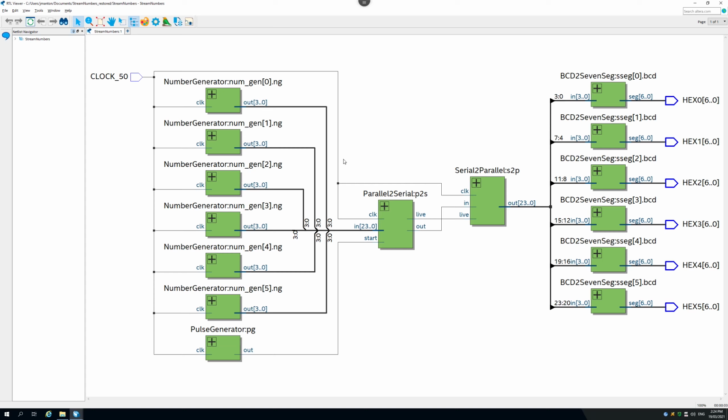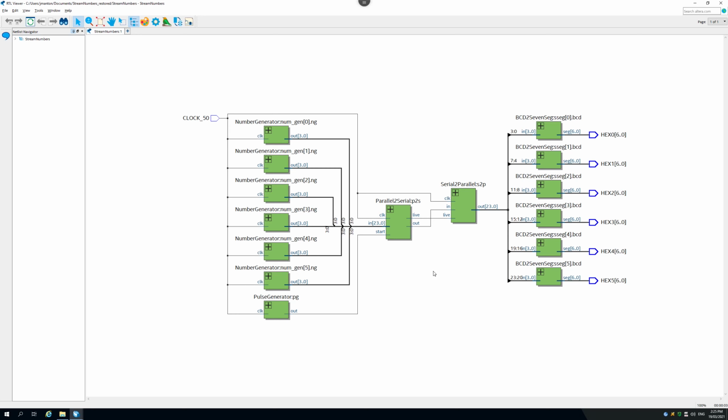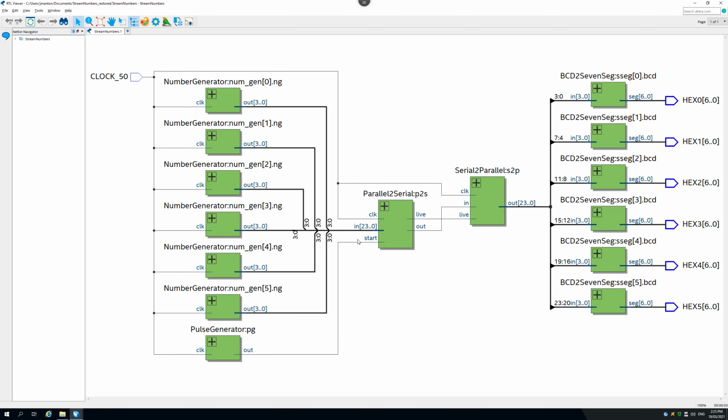Of course, we're using a common clock in our design. I've been mentioning that for simplicity. If we don't have a common clock, things get a lot harder, a lot more quickly. But with a shared clock, this serial to parallel and back again is relatively straightforward. Once we've received our data, if these chips are doing their job, then whatever number is coming in here should end up out here. So this should essentially be a transparent link if we're doing a good job.